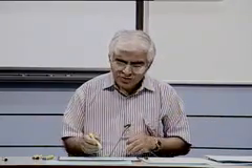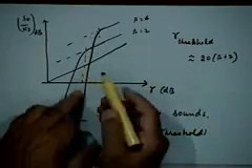At the same time, you don't want a large value of the threshold SNR, right? So you try to effectively reduce your value of beta for the purpose of demodulation, right? And frequency compressive feedback is a mechanism by which you can do it, and that is why it works. It's a preferred system when threshold effect is important to worry about.